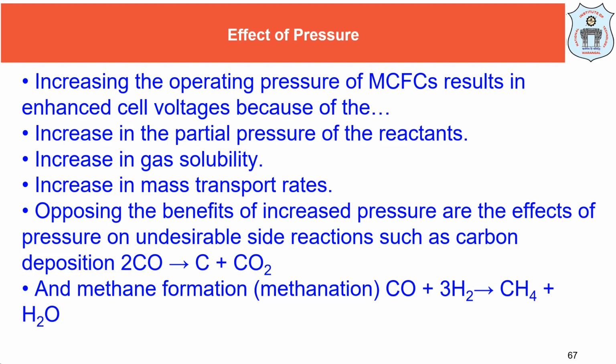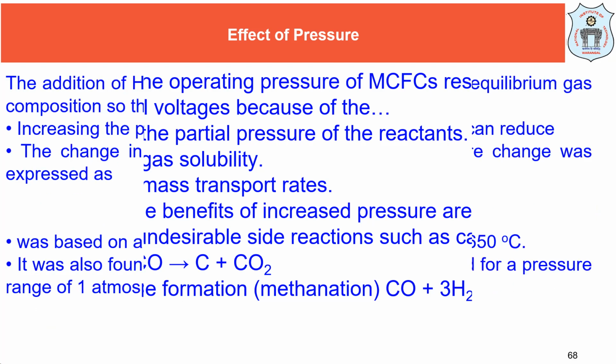Okay, and if you are using methane, a methanation reaction may take place with the CO being there. CO plus hydrogen will form methane and water. So that may be the side impact of increasing the pressure, rather than the other benefits that we are having. Okay, so we have some benefits and some demerits associated with it.